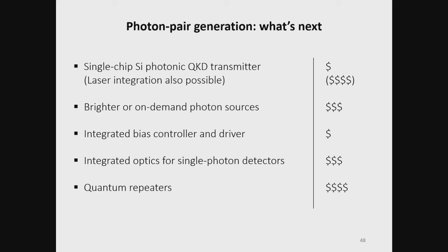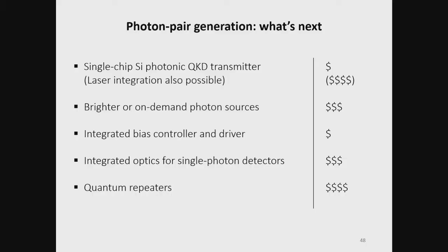Well, we have pushed silicon as far as we can, I think. Qs of 1 million being repeatedly made. Yes, you can get one-off results slightly higher. We have done oxidation of the sidewalls. We have done atomic force microscopy-based sculpting of silicon circuits. We've tried a lot of crazy stuff. You can see our papers. But I do believe that a new approach is needed, perhaps based on lithium niobate, now that we can bond that and use circuits.